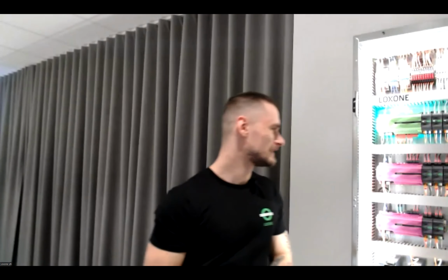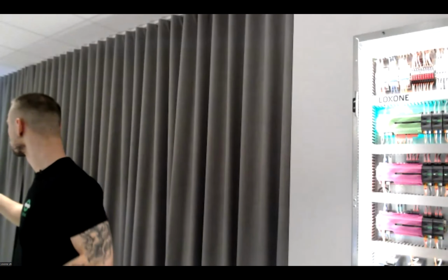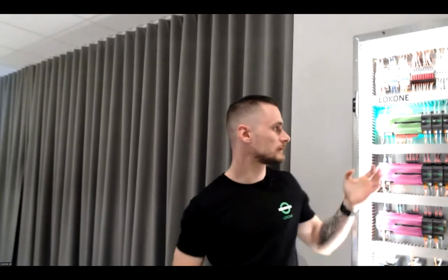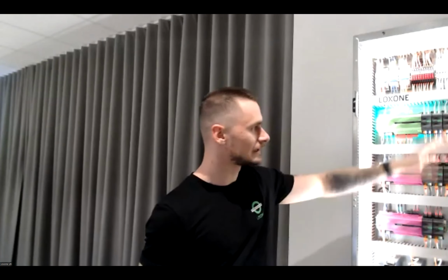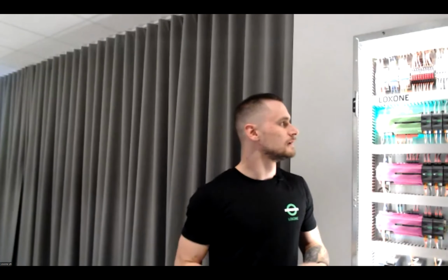Now, one more thing, as always. As you know, the pushing connectors on the mini server, or the pushing connectors on the audio server, any other device that we have, they're made for solid cores, and they're made for solid cores only. Plus, you can break them if you keep pushing in and out cables, or if the cable is far too thick. Now, that is why I have one more recommendation.